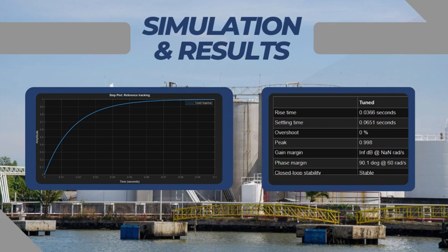The behavior will be as follows. Rise time: the time to rise to 90% of the desired value. Overshoot: the value that exceeds the constant value. Settling time: the time taken to settle to a constant value after the system has tried to work. Steady-state error: an error that occurs in the long term.